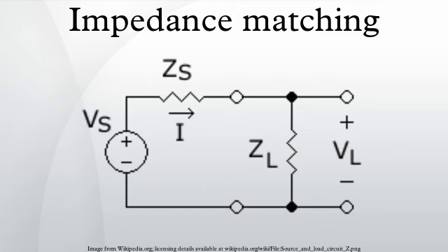The general form of the voltage reflection coefficient for a wave moving from medium 1 to medium 2 is given by the following, while the voltage reflection coefficient for a wave moving from medium 2 to medium 1 is as follows. So the reflection coefficient is the same, no matter from which direction the wave approaches the boundary. There is also a current reflection coefficient. It is the same as the voltage coefficient, except that it has an opposite sign.